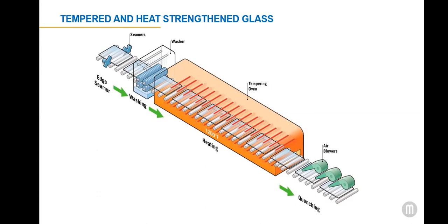Heat strengthened glass also provides resistance to thermal breakage caused by heat buildup in spandrel situations, and the probability of nickel sulfide inclusions introducing spontaneous breakage is non-existent in heat strengthened glass. Heat strengthened glass is often used in laminated glass because it allows better interlayer adhesion than tempered glass due to the flatter nature of the heat strengthened product.